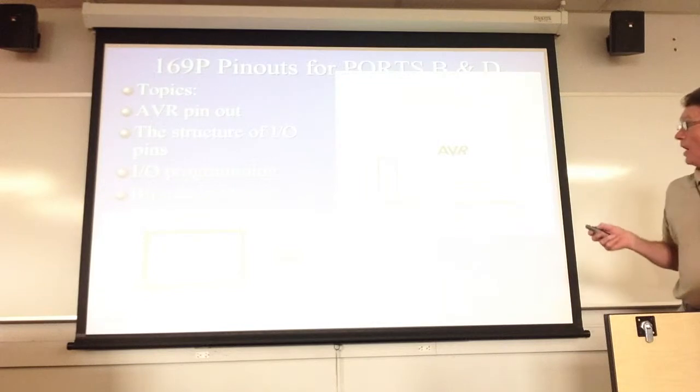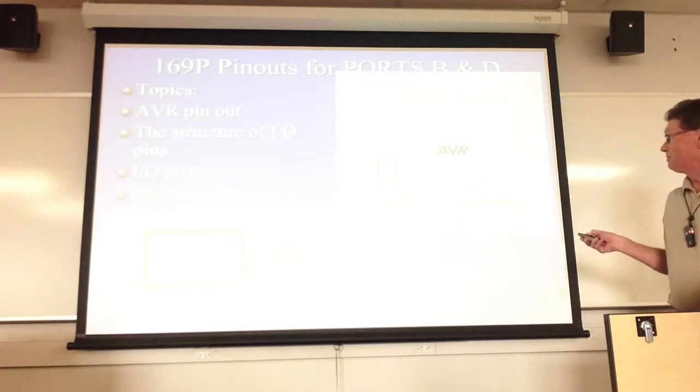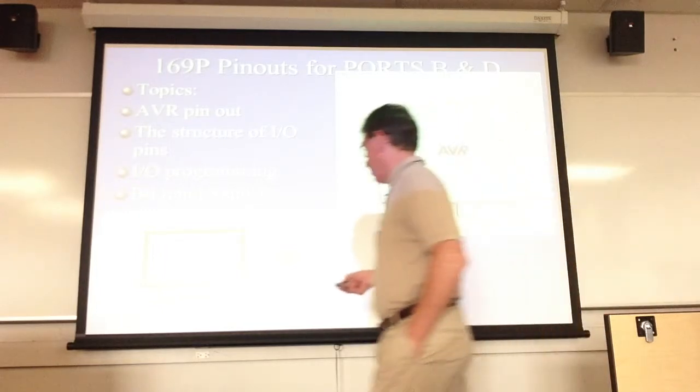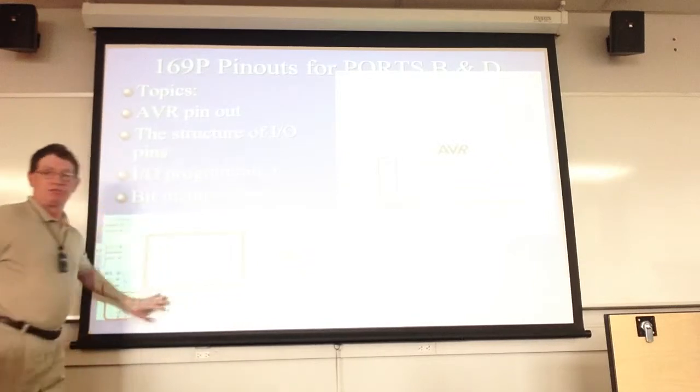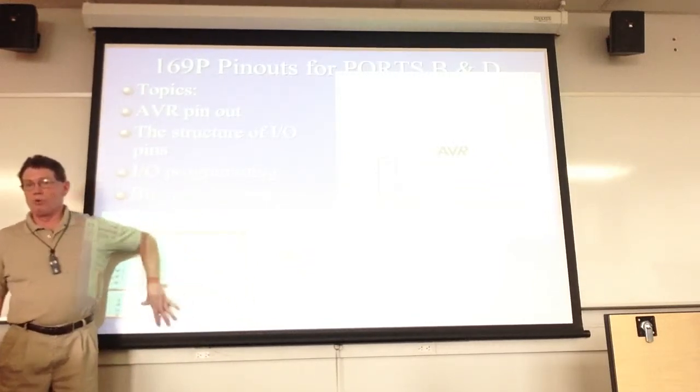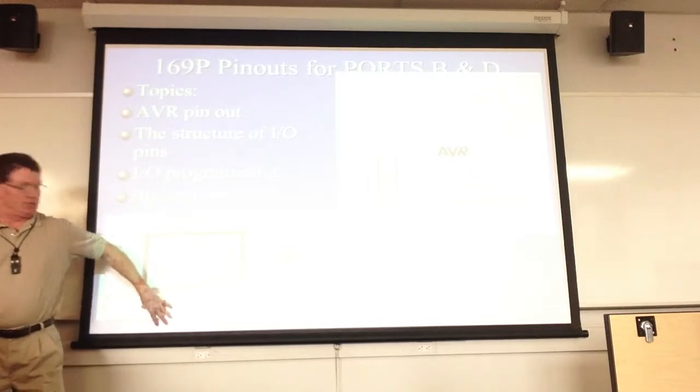All right, so we're going to do I/O programming. That's the whole idea here. I mentioned this the other day. These are your port D and port B ports right here, on the quad flat package. I'm going to be using these extensively during this part, port D and port B. I'm going to use port B and tie 8 LEDs to it.